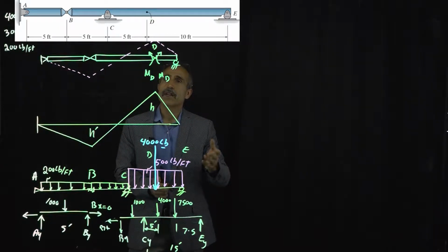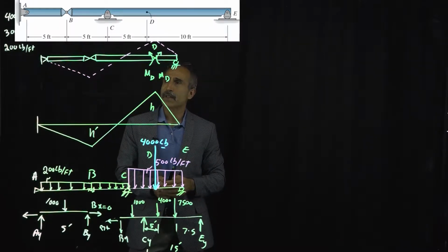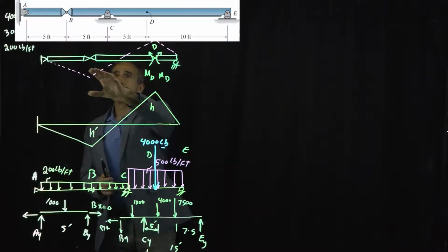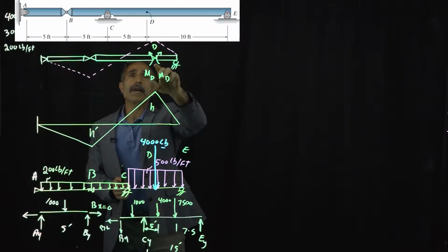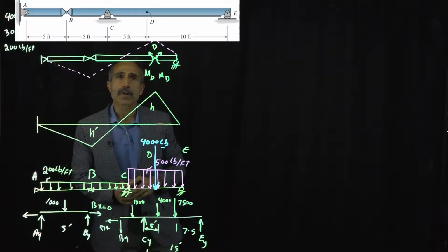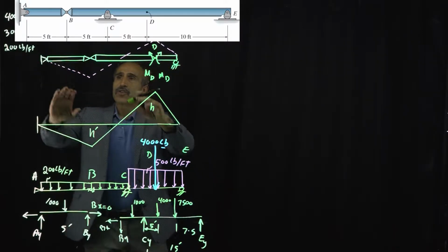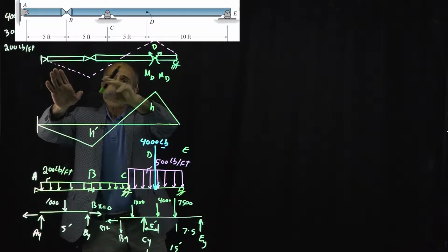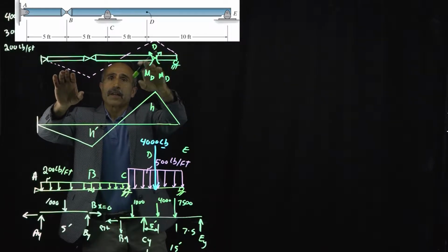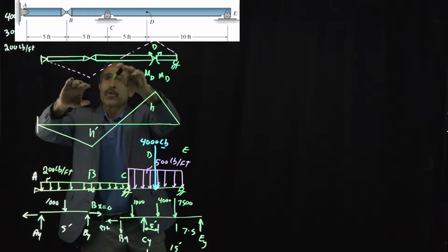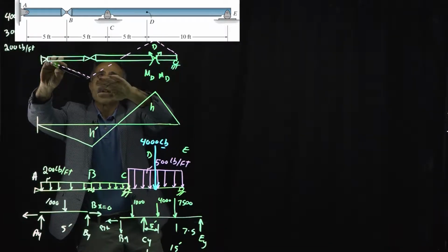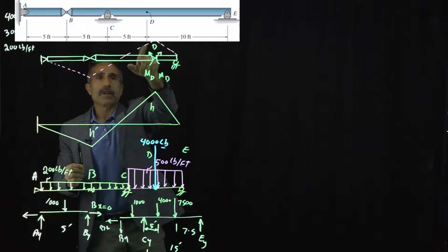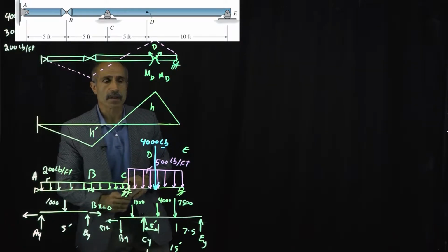But one of the things we talked about before is the influence line. If we make the cut at D, replace it with a pin and apply a positive moment, then we can draw our influence line. It's the deflection shape of the beam when you make that cut, and you have your beam kind of drop down.